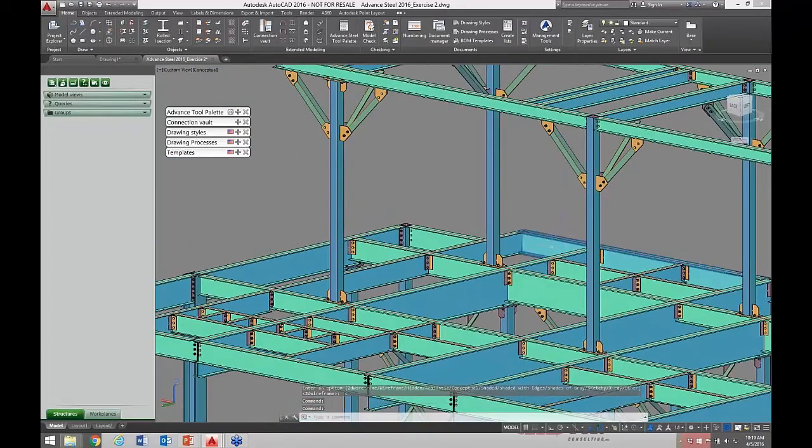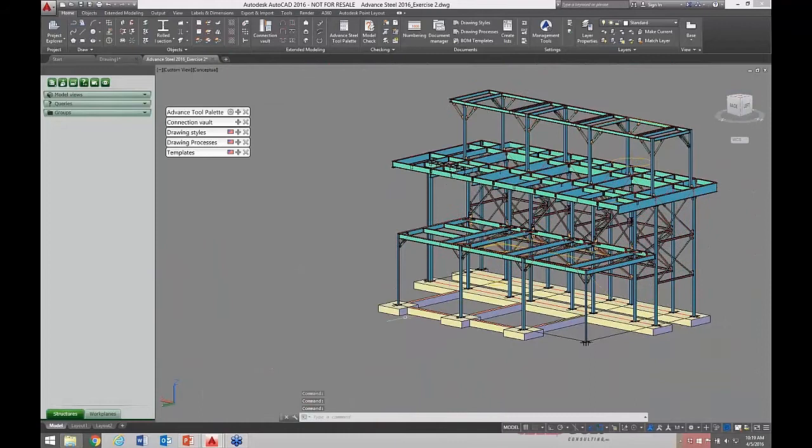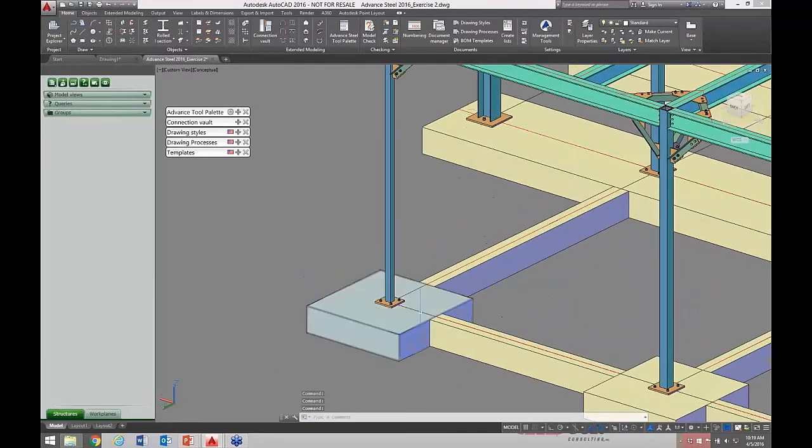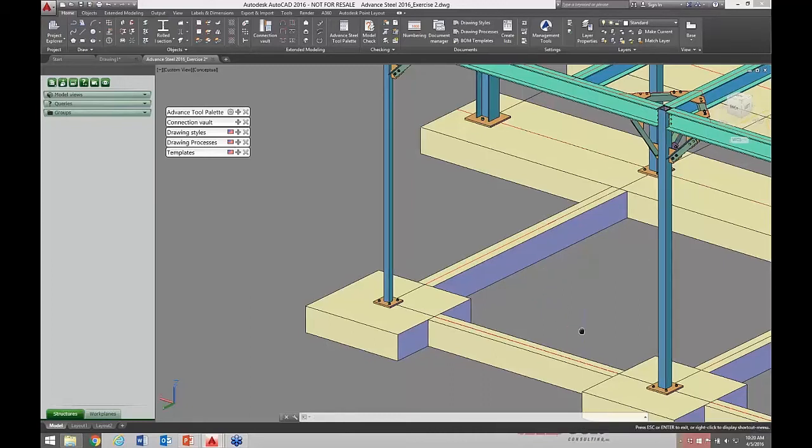We see a few bracings. If I pull out far enough, you can see that there are some concrete items. I'll add a concrete pad for us in beam, and especially other shapes we could add, like a concrete wall, whether it's representing a tilt-up or cast in place. And I have embed plates that I'm wanting to detail out and develop connections for. I can have those elements placed in my model and actually get it to cut voids and create things for me so I get an accurate representation of that embed condition.